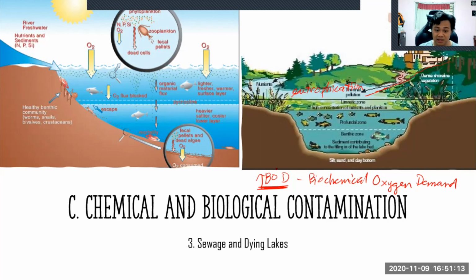Because as BOD goes up, dissolved oxygen goes down, all right? Because it uses up the dissolved oxygen in your bodies of water. So that's how important it is to remove those nutrients before dumping it into bodies of water. I will explain further in the later part how this is being done.